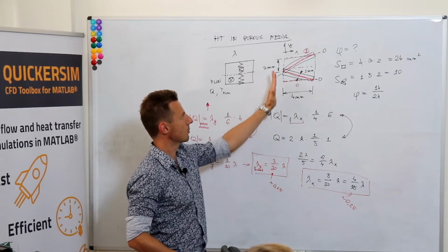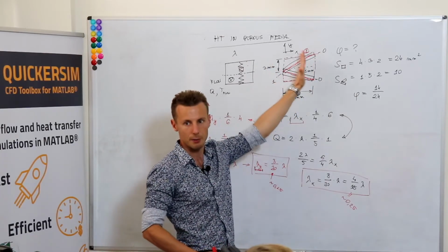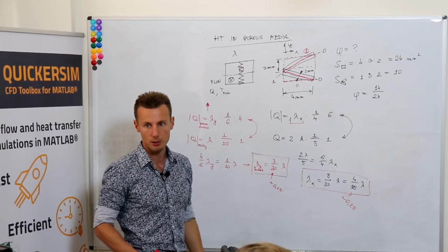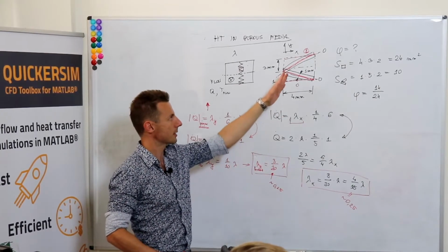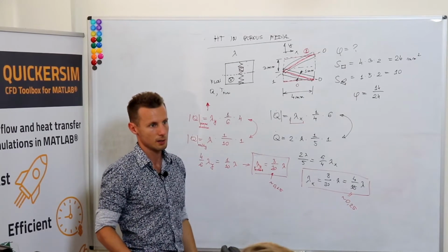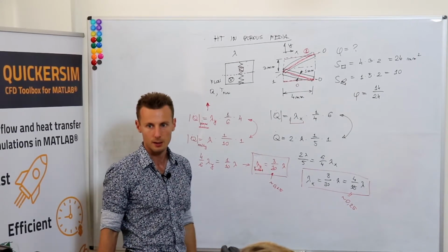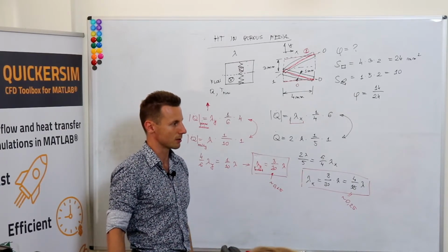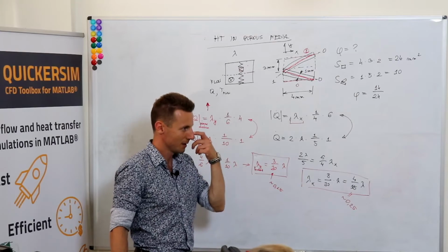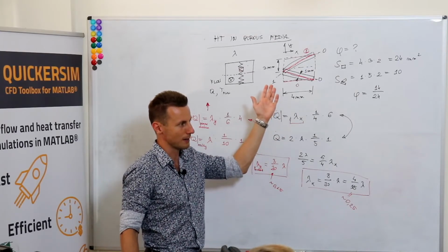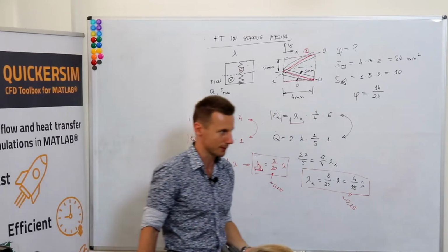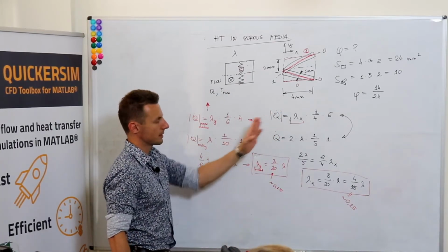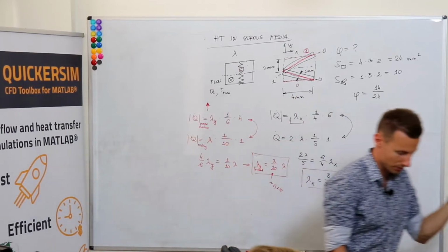And then let's assume that we've got temperature gradient only in this direction to calculate the thermal conductivity in the x direction. And air is assumed to be adiabatic, like it does not conduct heat, and that's very, very often true. Like the heat conductivity is 0.025 compared to any metal, which would be in the order of 100. So that's really nothing. So that's the first step. What's the second step?